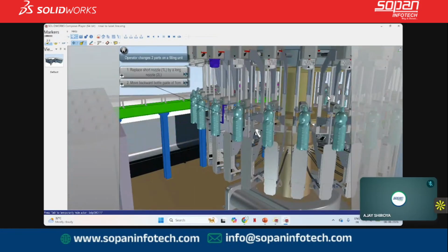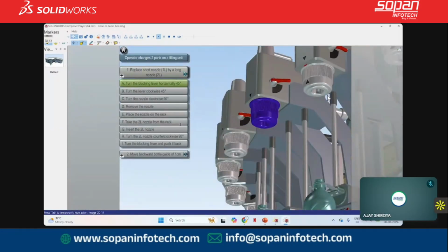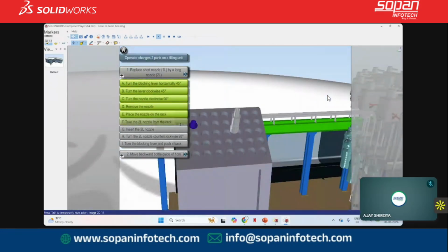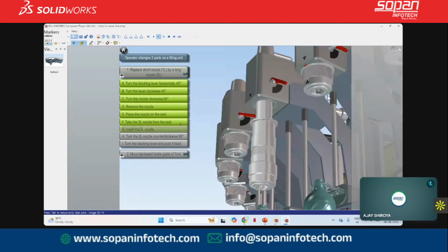So how does the whole filling machine area look? Then I want to replace the nozzle. How can I replace it? Turn the blocking lever horizontally by 45 degrees, turn it clockwise, then remove it, put another one back and insert the second liter nozzle. Turn the second liter nozzle clockwise, then turn the blocking lever to push it back.